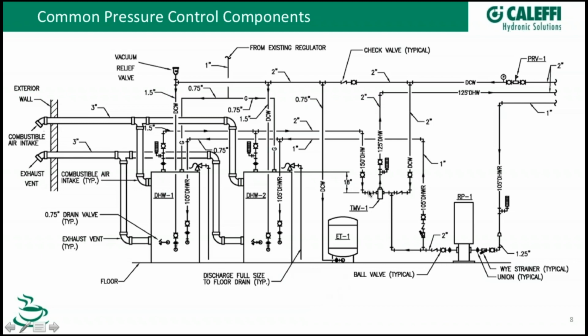You'd have your mixing valve for your temperature mixing. You'll have your expansion tank. You've got your recirculation pump. You'll see some temperature gauges, some isolation valves. In fact, what I'll do here is I'll toggle on exactly the components that we're going to talk about today, and you can see where they fit in a piping system, where the correct placement would be, downstream of the check valve on the expansion tank, so it can handle an expansion of the tanks. T&P valve typically here for both temperature and protection for this vessel here.